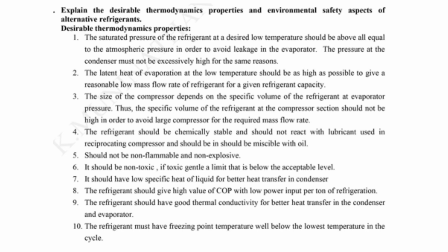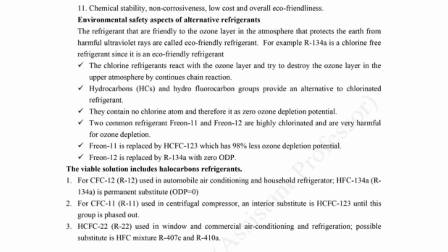The refrigerant should give a high value of COP, with low power input per ton of refrigeration. The refrigerant should have good thermal conductivity for better heat transfer in the condenser and evaporator. The refrigerant must have a freezing point temperature well below the lowest temperature in the cycle.